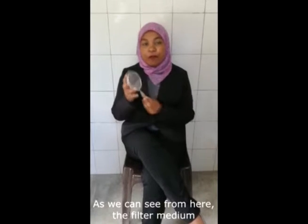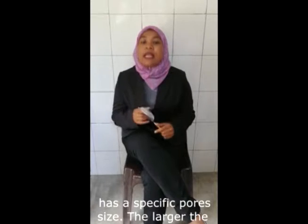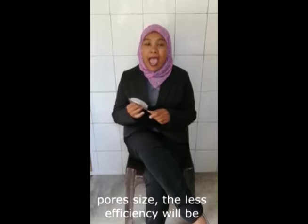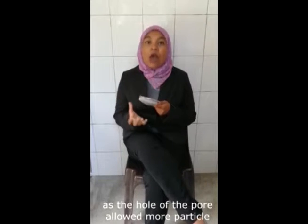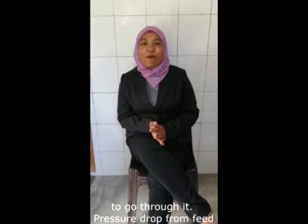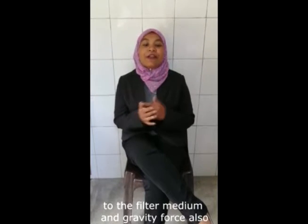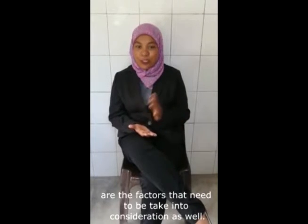As we can see from here, the filter medium has a specific pore size. The larger the pore size, the lower the efficiency will be, as the larger pores will allow more particles to go through. Pressure drop from the feed to the filter medium and the gravity force are also factors that need to be taken into consideration.